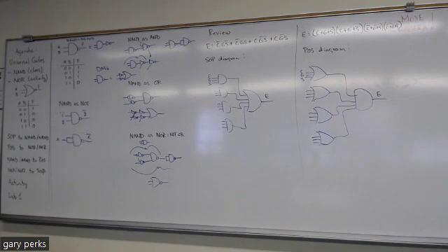The main reason I'm putting those back up here is because I want you to compare NAND, NAND, and NOR, NOR to those once we know what NAND, NAND, and NOR, NOR are. So let's go ahead and talk about them. First I'm going to show you how to get NAND, NAND from an SOP equation. Then I'm going to show you how to get a NOR, NOR from a POS equation. Then we're going to do a couple of examples. One's going to be NAND, NAND to POS, and one's going to be NOR, NOR to SOP.